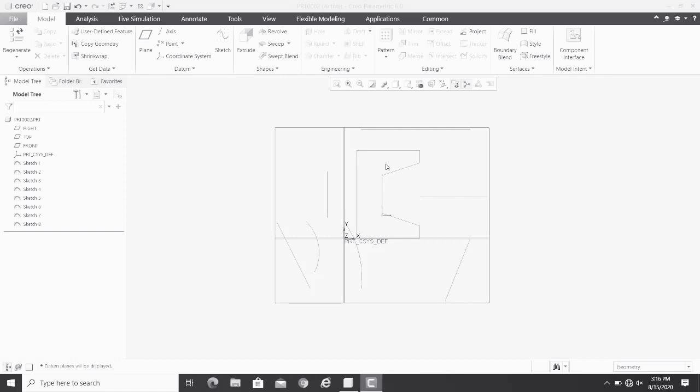Normally, what you will do in a revolve command is make a sketch, and then revolve that sketch around a certain axis. So the requirement to complete a revolve command is the selection of two entities. You have to select a profile and then an axis of rotation for that profile, so that we can revolve the profile around the selected axis at any angle.